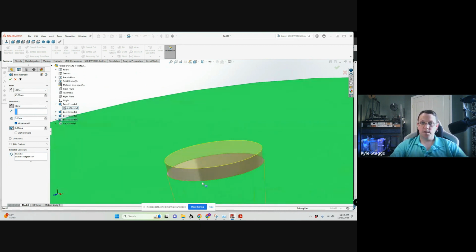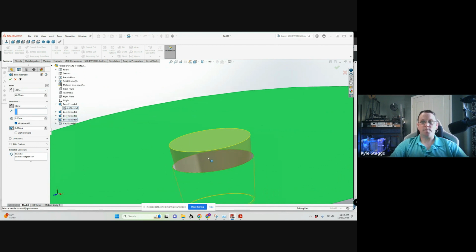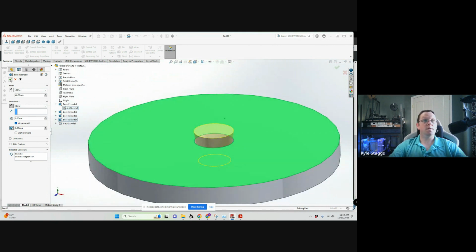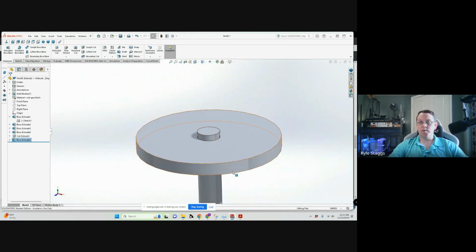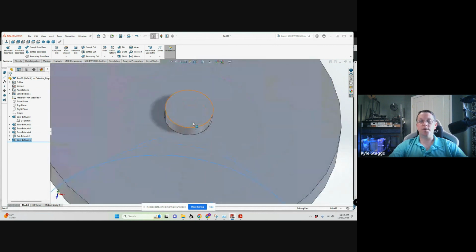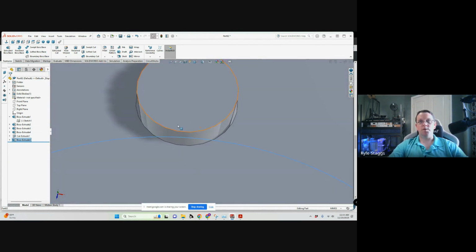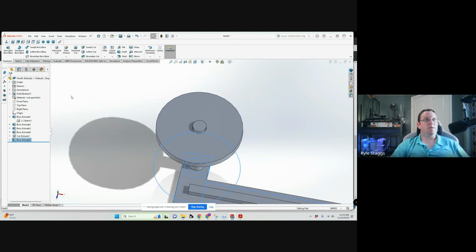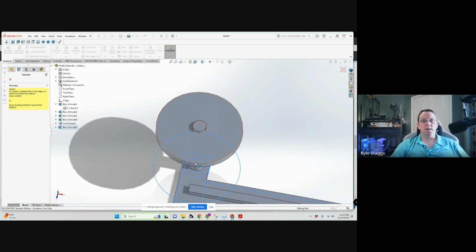We can even increase it by a couple more. 46 and 6 millimeters. What this does is create a gap in the part, so that those two, depending on the resolution of the printer, shouldn't be completely fused together.